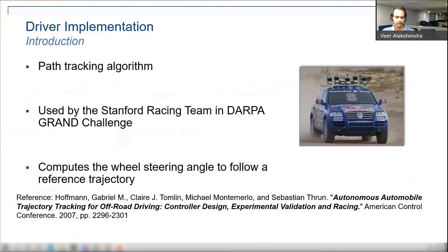It's what I would call a lateral driver, or a geometric driver, called the Stanley controller. They are different: there's Pure Pursuit, there's Stanley, then you have MPC also. A lot of people are using MPC as well. We are just focusing on this driver implementation, the Stanley controller, which was first introduced in the DARPA challenge by the Stanford Racing team. To learn more about this, we have provided the link. However, the important thing is how we implement that in the Simulink model.